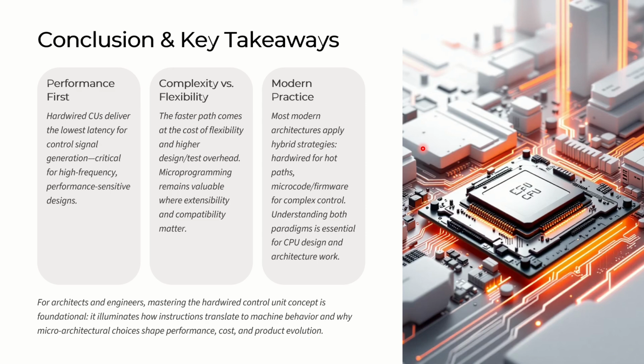Performance first. If you are moving towards performance, hardwired control units deliver the lowest latency for control signal generation, critical for high frequency, performance sensitive designs. The second point is complexity versus flexibility. The faster paths come at the cost of flexibility and higher design overhead. Microprogramming remains valuable where extensibility and compatibility matter.